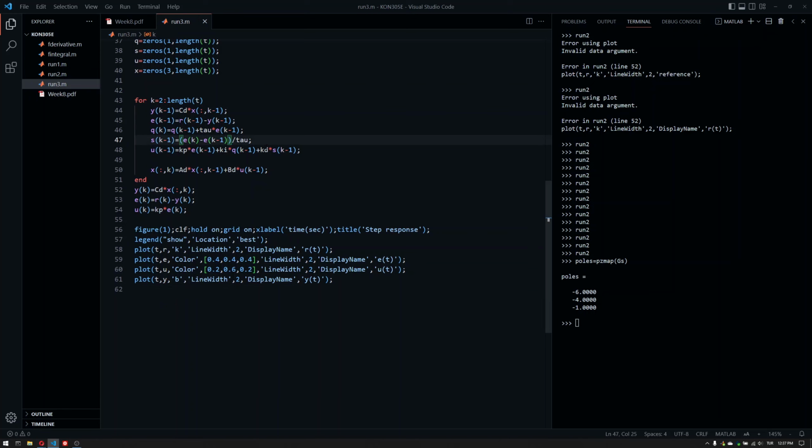Because when we talk about PID controllers, we always talk about the fact that they are not quite realizable. And the reason for that is we need prediction. But the way that we overcome prediction is basically we're looking at the previous differences instead of looking forward. We're looking a little bit backwards instead of predicting the future, if that makes sense. And this is also the equivalent of a sort of derivative.